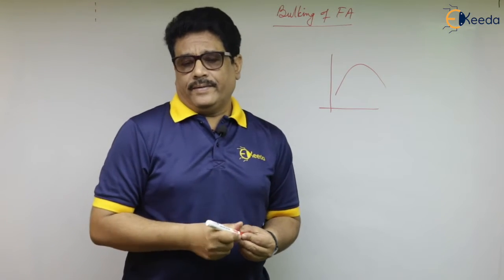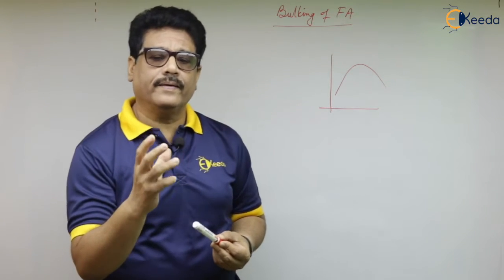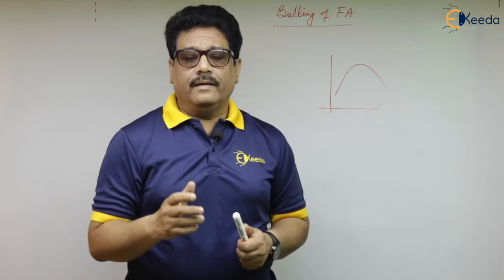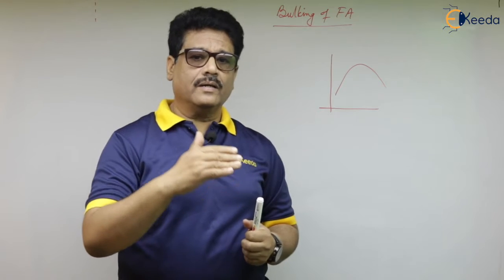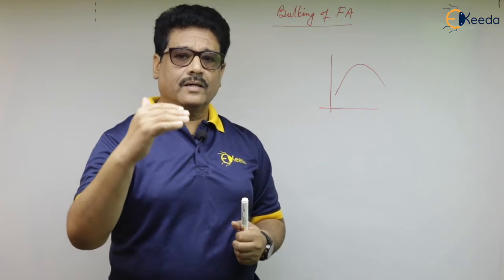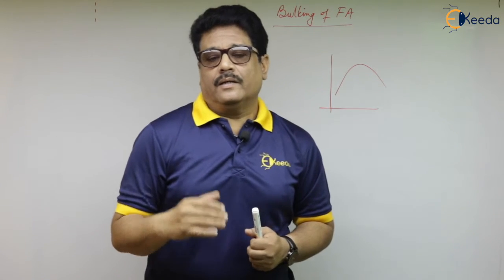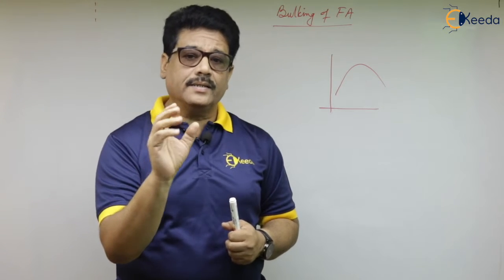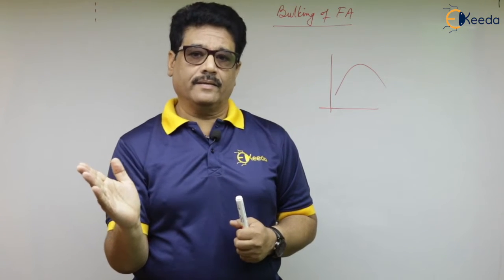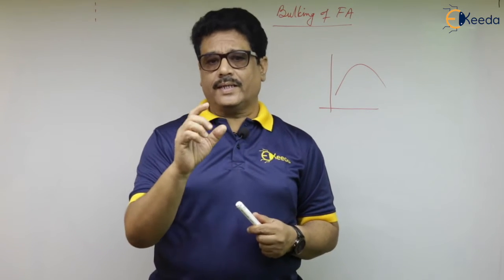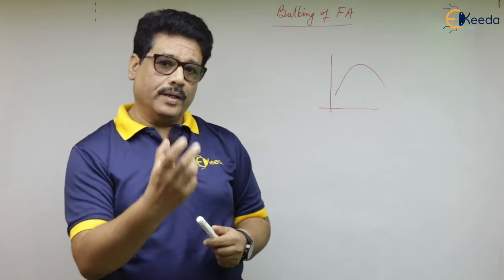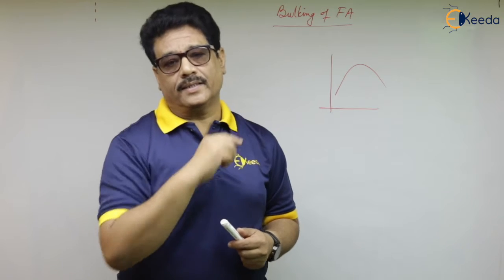So definitely you have the effect of bulking. Generally, sands may be fine sand, medium sand, or coarse sand. Coarse sand is on the benefiting side for the contractor or for the project, because coarse sand has a lesser tendency to bulk than the finer sands.